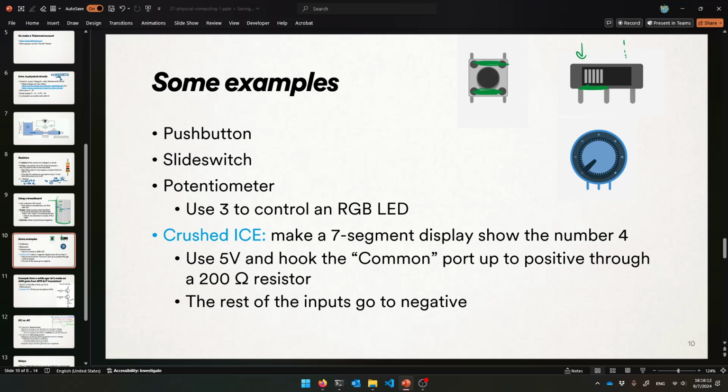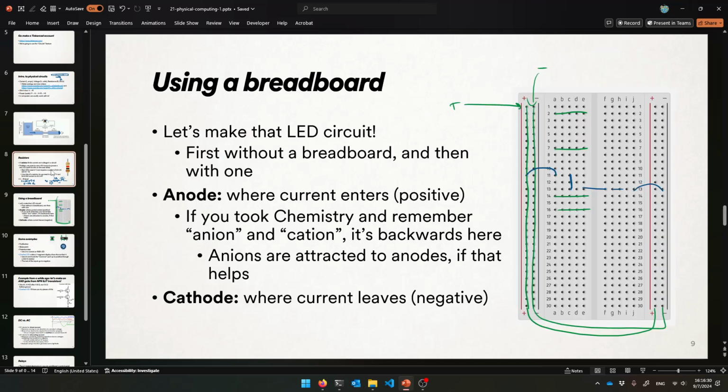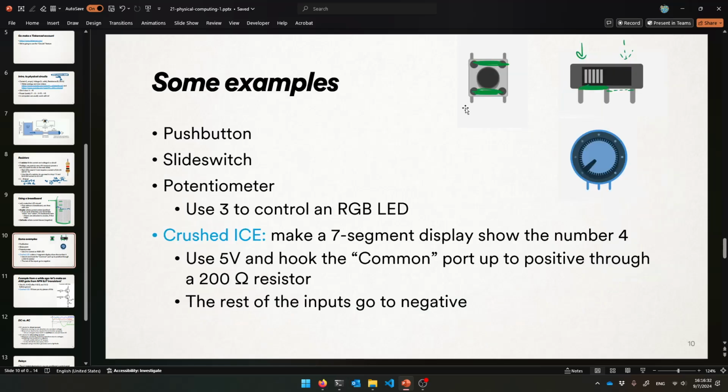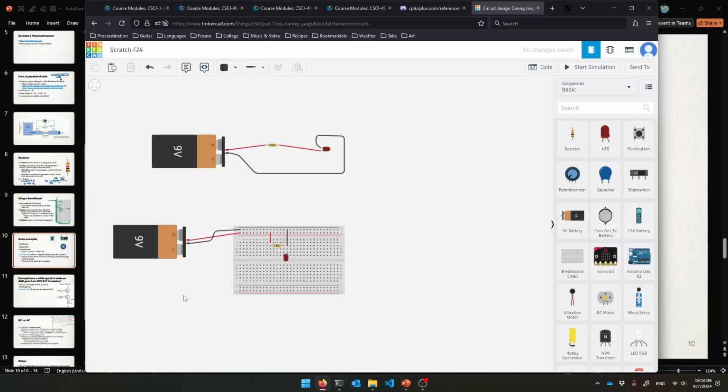Or if it's over here, along the dotted arrow, if you flip it in this direction, it cuts off these guys and powers this one from here to here. I hope that makes sense. So you can do two separate things again, which is kind of cool. So that's a push button and a slide switch. Let's bring in an LED again and light it up when we press the button or flip the switch. I'll do it with a different breadboard.